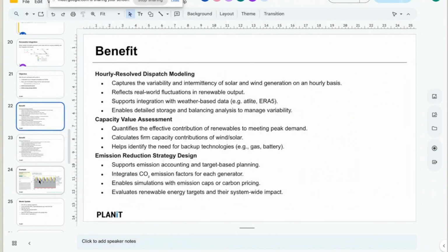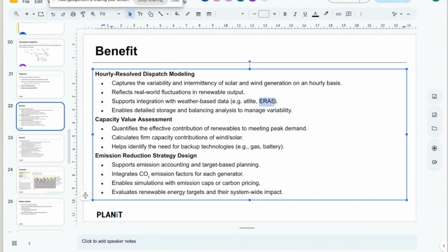So this model is basically based on an hourly system. Here we used Renewables.ninja to get the PV and wind profiles. However, there are some other options. For example, you can use the ERA5 database as well. I'm going to explain the difference during week 5, but ERA5 was quite popular, though it has its own problems, and Renewables.ninja has been more popular these days.